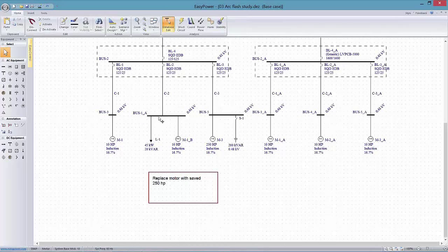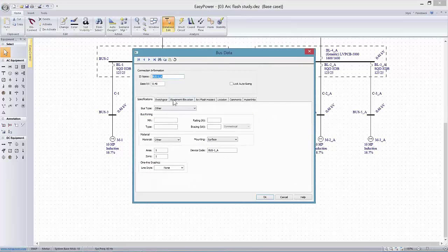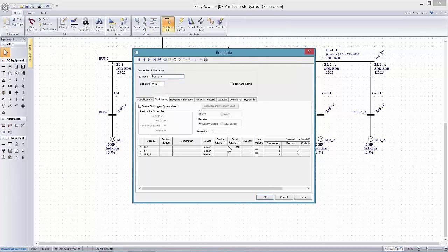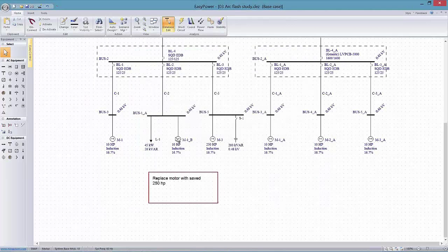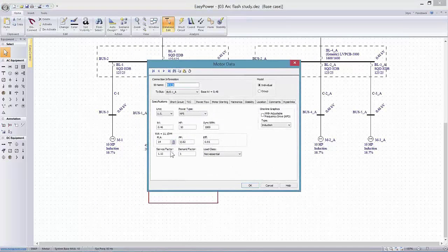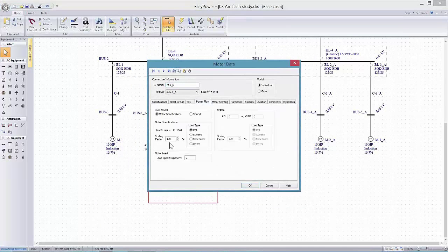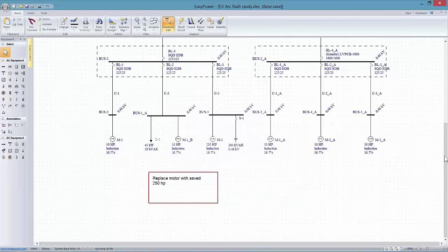Diversity, yes, I think it can be interchanged with scaling. It shows up on a display for switchgear because these can be dealt with on a global basis, whereas for an individual motor, the scaling factor handles it as we're analyzing power flow for that particular motor. So I take that back. Scaling factor and diversity are similar.